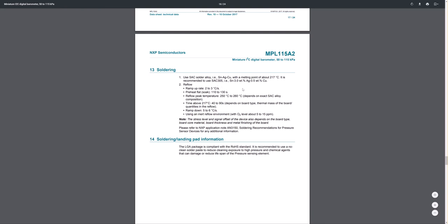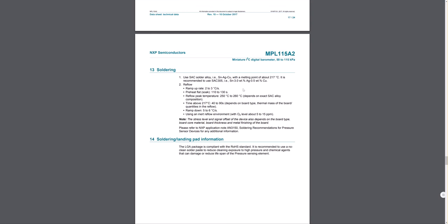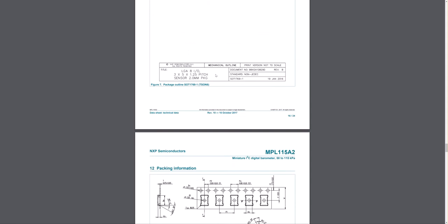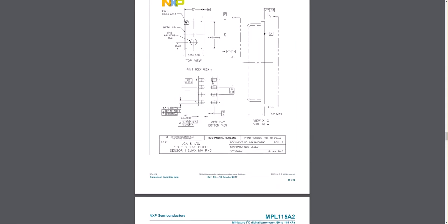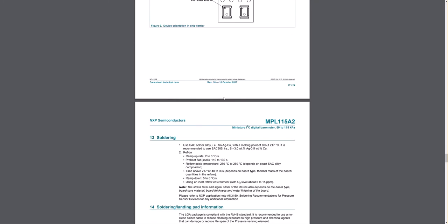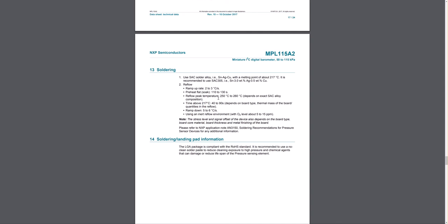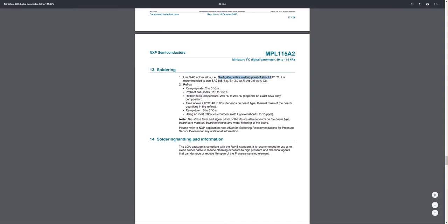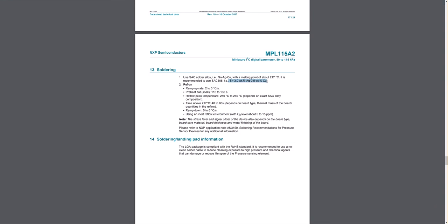And if you're talking about soldering these by hand, well, one, it would be very difficult because of the pad location. It's not impossible, but it would be very difficult because they're located underneath. So this is usually done via machine, and they have the solder paste down, and then it's saying the solder paste that you should use should be kind of this right here. This is the one they're recommending. Now, it's not to say you couldn't use different solders, but this is the one they're recommending.